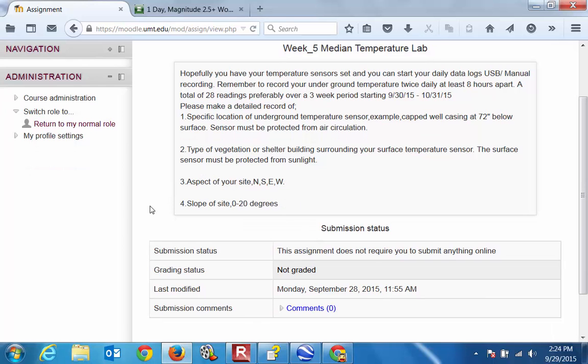So that in most places, I've seen places where if it's compacted soil and it's moist, like in a roadway or something where they've dug a ditch and they've tried to put a pipe in at 10 feet or whatever, and it gets pounded and it goes to 40 below zero and the pipe will freeze at 10 feet, because of the moisture in the soil that conducts the cold.